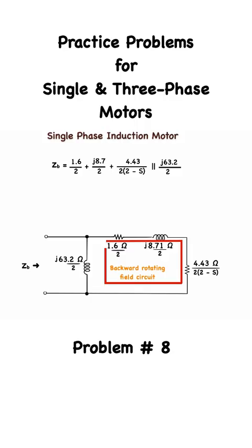Working out the series parallel combination, we get 4.75 times 31.6 divided by 1.93 plus J 4.34 plus J 31.6. Keeping in mind that we are working with the rules for phasor arithmetic, we finally get 1.49 plus J 3.89 ohms in rectangular coordinates, or 4.17 at an angle of 69.04 degrees in polar coordinates.